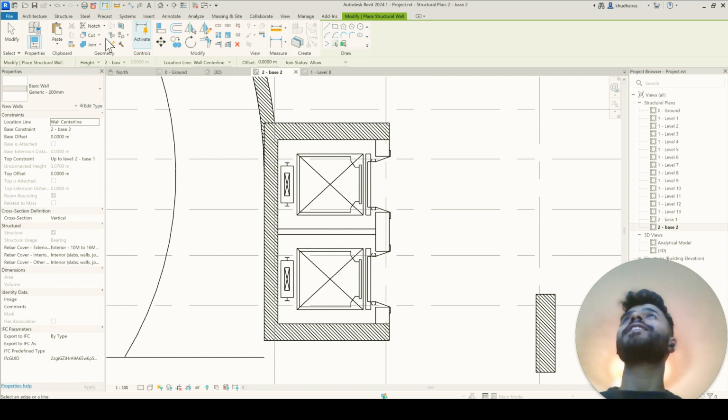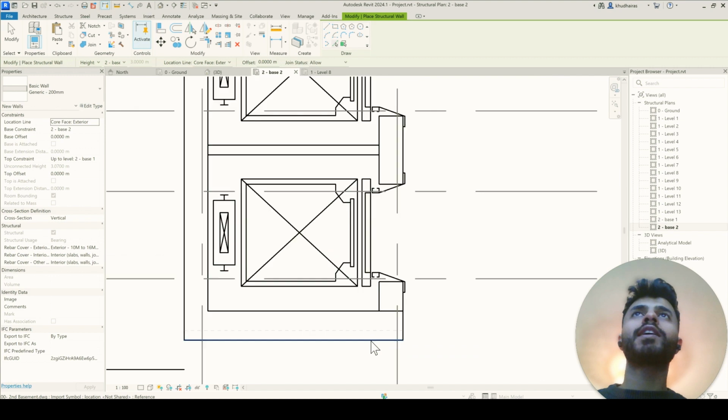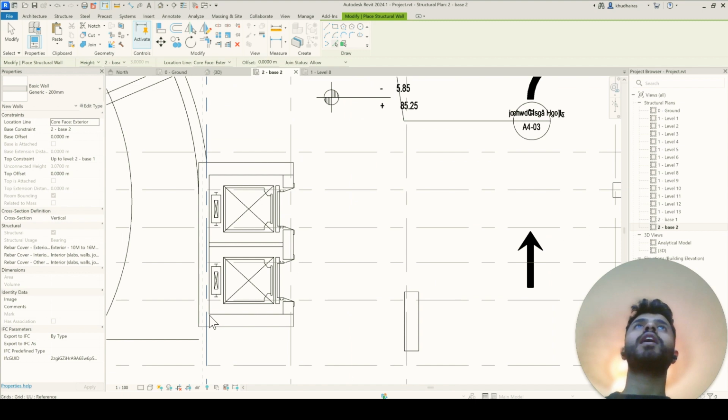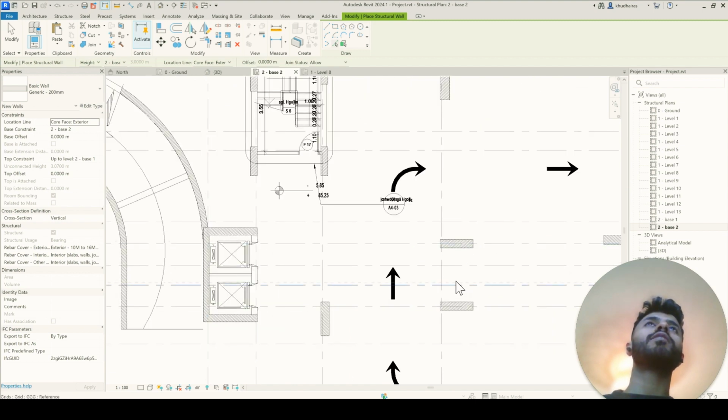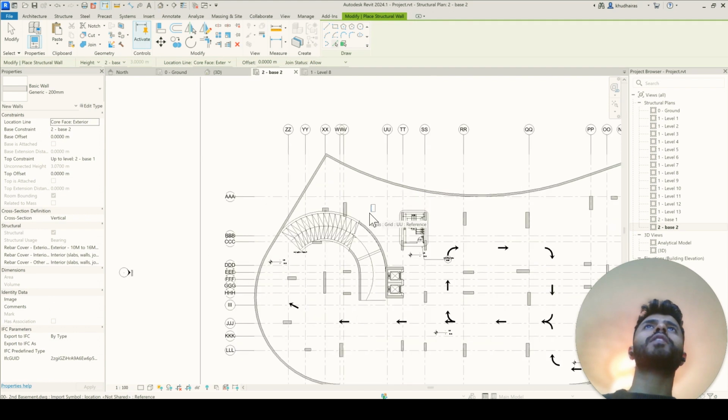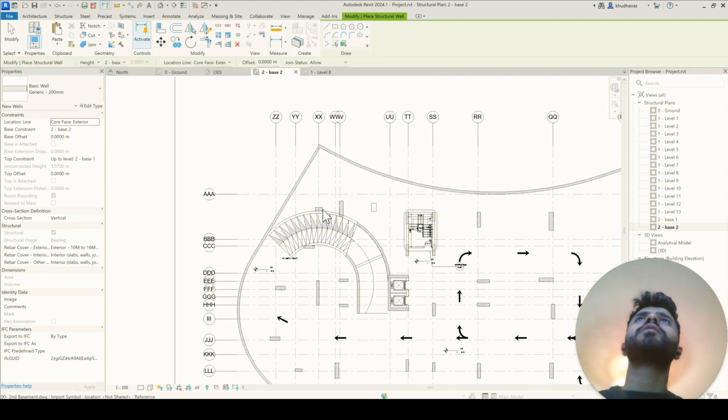And if we stand here, you see there's a shaded line. So all hatched columns are structural elements. So these are load bearing elements. And the non-hatched columns or walls are not carrying any load. If you look here, for example this one, they are more for architectural purposes. So we have to make sure we select the right one. We are in Revit structure, so we need the things carrying loads. That's the important one in our design.